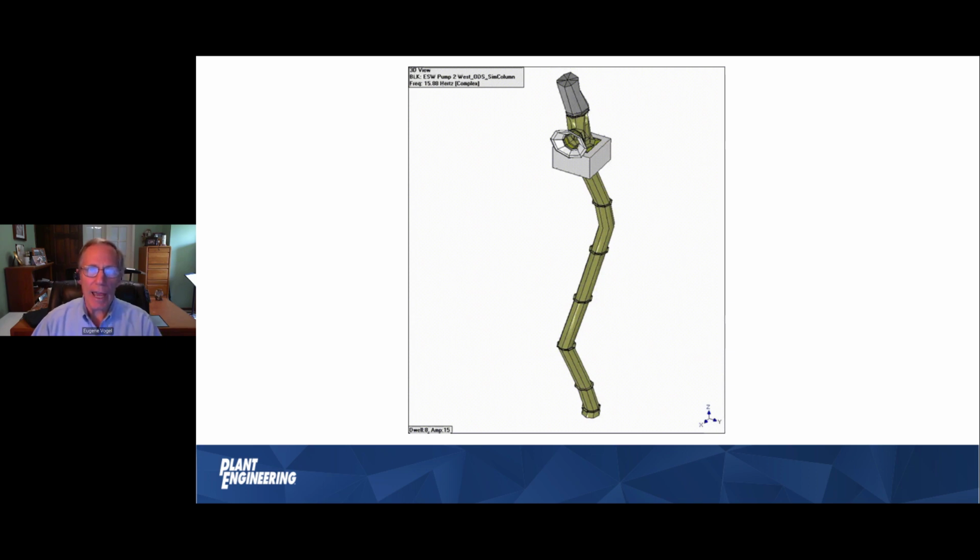Be aware that the animation has the ability to illustrate and change the amount of vibration. That could be a very slight amount of vibration, maybe not damaging the machine at all, but you just crank up the amplitude on the animation and make it very severe. That one's cranked up a little bit too far. Okay, just to show you what's going on. So an important point, when you see a machine doing a dance like that, it doesn't necessarily mean the machine is flying apart. It's just an animation.